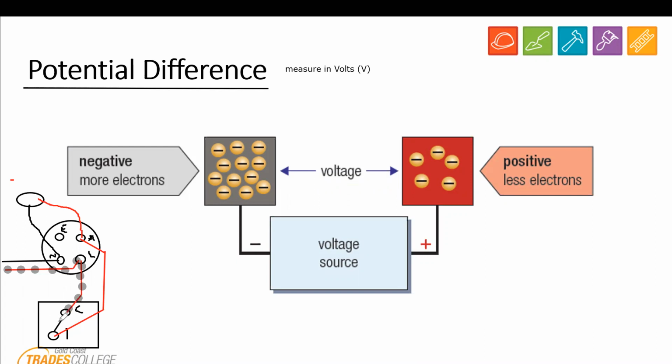It's going to then go through the switch, up there, through there, which is our switch wire, and then to there, where it switches the light on, and then it has its return there through the 0, all the way back. All right, and that's a closed circuit, okay?